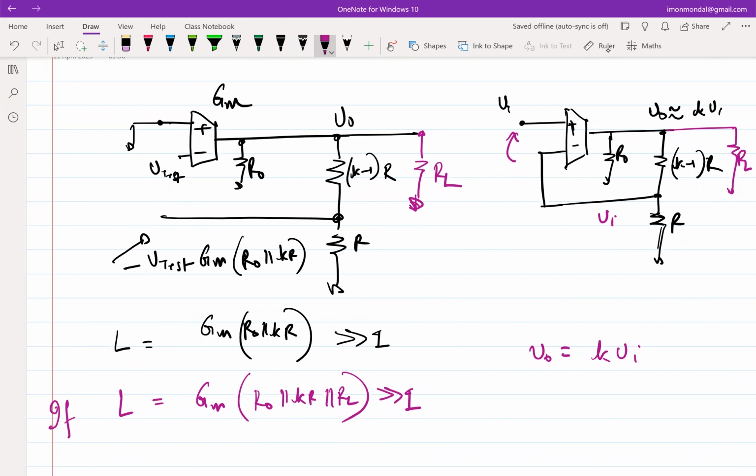Negative feedback works with the principle that it has to track the error and drive the error towards zero, regardless of what you have connected anywhere in the network. And wherever you have injected any disturbance, it doesn't really matter. The only thing that is sacrosanct is that the input to the error amplifier should tend to zero. If you can ensure that, then you get what you want. Okay, does that make sense?